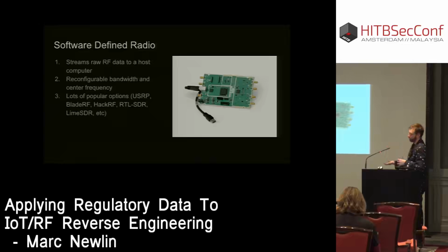And again, with SDR, we can configure it to be whatever physical layer we want. So in this case, we can tune it to the specific frequencies that the mouse is likely to use and define using GNU Radio how we're going to demodulate the data.